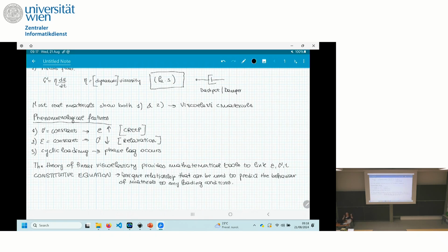You extract the material parameters from the first test. You use those extracted parameters. You ask your model, can you predict the response, for example, to creep? And that must match the second experiment set. If you don't do that part, you've just fitted your data. It's a good fitting function, but that can be anything.